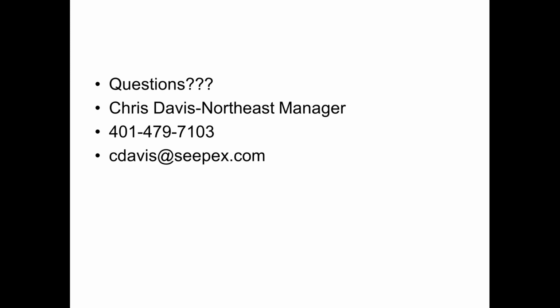What is the maximum suction distance Seepex can handle? 27 feet, and that is all depending on NPSH-A. What is NPSH-A? Net positive suction head available in the system. So when you say 27 feet, do you mean a 27-foot draw from a pit? Correct. So if you were in a perfect condition with the perfect pipe diameter, the longest suction lift that Seepex has done is 27 feet.